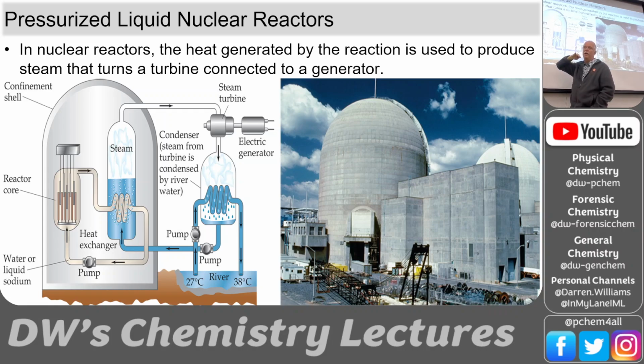So we're working our way up that liquid-vapor equilibrium line, and we're not letting it be vapor, it's all liquid. And so when it gets over here to this heat exchanger, this water flashes to steam. So we're just moving the heat from the nuclear core over to this heat exchanger and making steam over here. So the steam loop is also closed, and it's not connected to the nuclear fuel. It's just connected to this heat exchanger. So it's not radioactive.